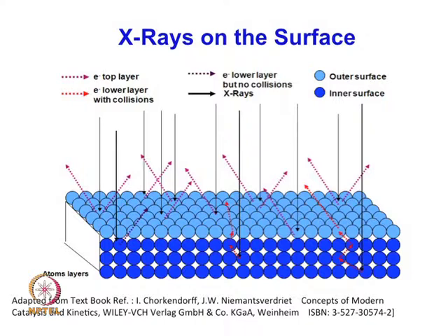Whatever analysis you can get, it is the phases which have been formed, based on the diffraction angle or the intensity of this radiation, the secondary electrons. When you have XPS, the information can be obtained in terms of the binding energy of that electron. So, different types of information can be obtained from primary, secondary or energy beams, Auger electrons, or the diffracted electrons. But when you use X-ray, you have just the surface information, in terms of the crystallographic nature and crystal structure.